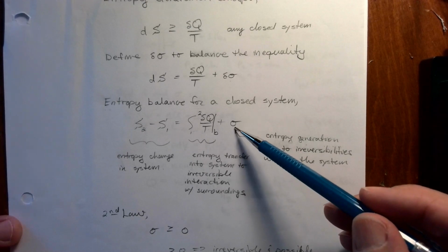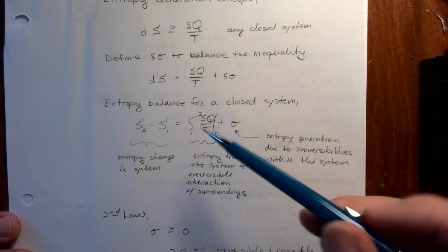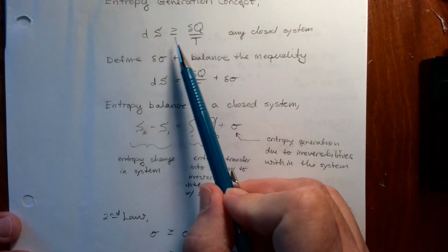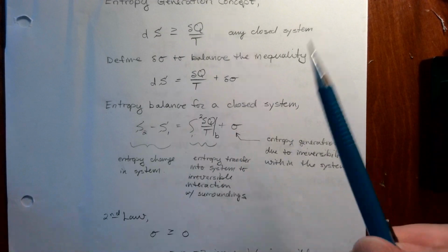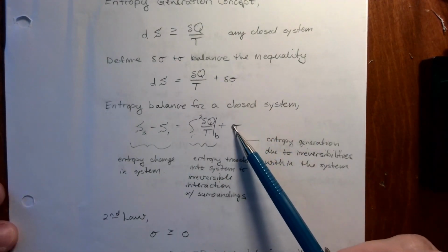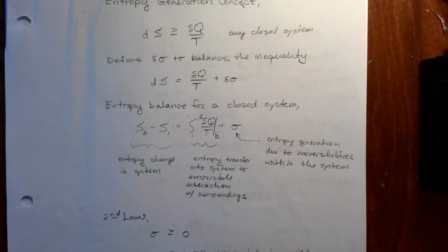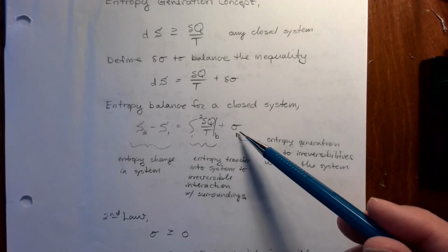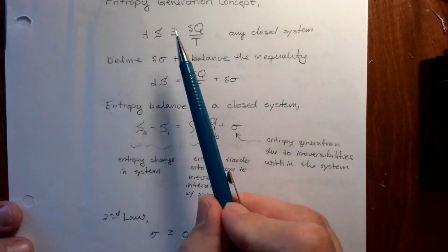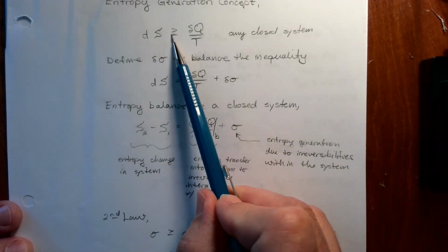Okay, so if sigma is 0, then we have an internally reversible process, right? If this is an equality up here, then this must be internally reversible, definition of entropy, if you guys recall. If sigma is positive, then this will be larger on the left-hand side, and then we have a possible process, theoretically possible according to the second law. If sigma is negative, then that would violate the second law. I'm sorry, this is less than 0 up above and would violate the second law.